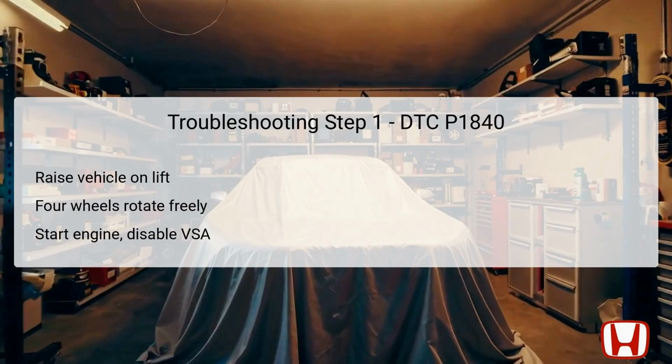Following this, start the vehicle engine as part of the confirmation procedure, making sure to disable the Vehicle Stability Assist (VSA) system. Disabling VSA ensures that it does not interfere with the data being gathered, allowing for accurate evaluation of the CVT system's performance under normal conditions. Proper execution of these steps will set a solid foundation for the rest of the troubleshooting process.